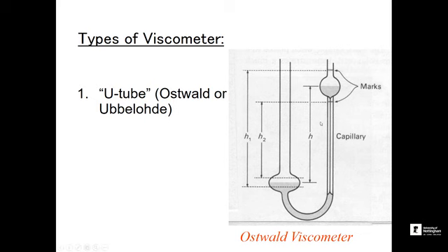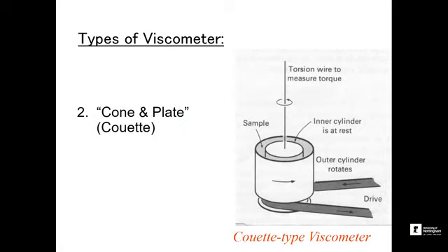Okay, so you pump the liquid through. When it gets past this top mark, you stop pumping, and then you let the thing just relax back under gravity. And it takes typically a minute, 2 minutes for water to go from here to here, because the capillary slows the process time down. And you just simply time how long it takes to get from there to there, with a stopwatch or using photo sensors. That's the Ostwald viscometer.